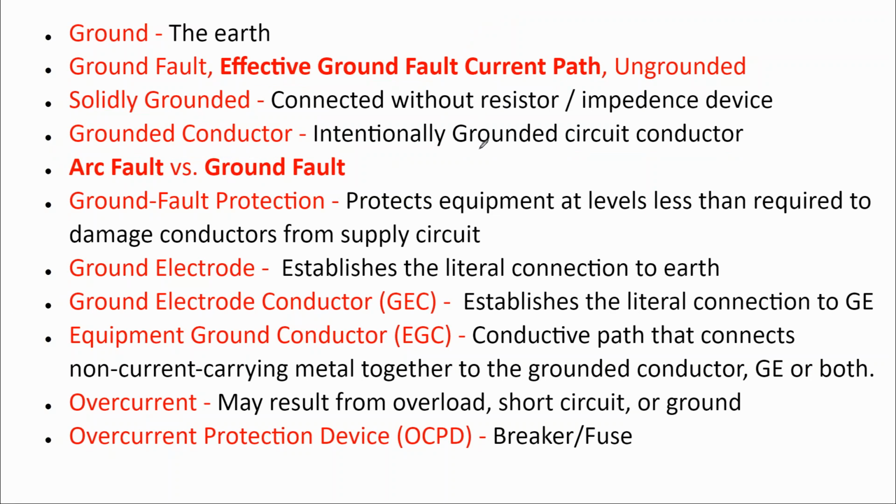Now that connection, that intentional grounding, is only made at one point, because we want a funnel. We don't want a sifter. We don't want the electrons just to flow out in any direction. In fact, a drain would be an analogy. The final ground on a home needs to be a lot larger than the ground paths for the effective ground pathways for the individual devices.